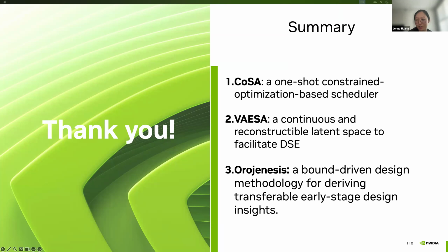But another interesting part is if you want to optimize for latency, so for energy, then you might need to also do some iterative solving at different memory level stages, because you really want to encourage more traffic to the innermost buffers. And what we didn't solve in the COSA paper is multi-level memory backing store solving. We basically only focused on the DRAM to global buffer and global buffer to the NOC, but nothing within this PE memory hierarchy. But in order to solve for the best energy, you probably need to do some multi-level solving, probably with iterative solvers.